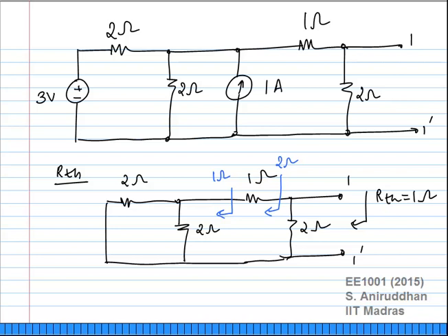if you have a lot of sources, what makes sense is to apply superposition between those sources. Okay, apply each source in turn. You will be able to reduce the network. Okay, find out the voltages across each resistor or the current through each resistor and so on, and figure it out. And finally, add all of them, right? Apply each source, whether it's a voltage or a current source, in turn, and add all those voltages.